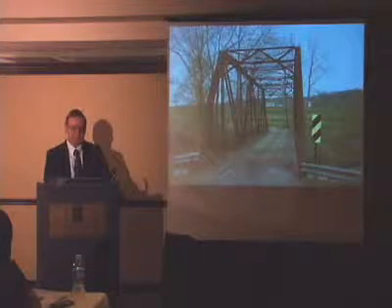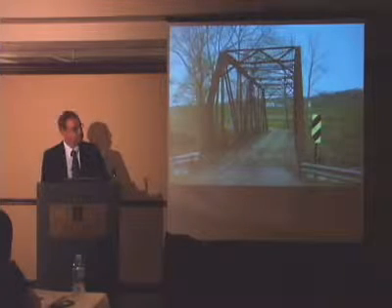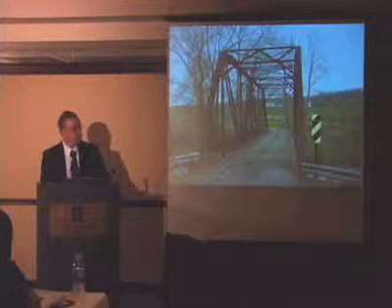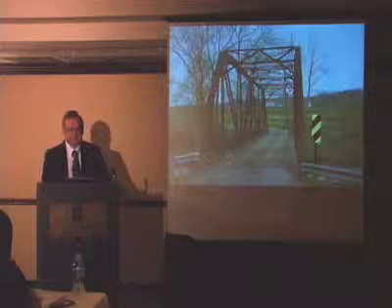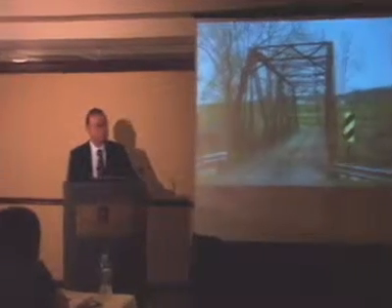So we took the bridge down, completely rehabilitated it. It was actually an old interurban train bridge. It carried interurban train cars, and so it was pretty heavy duty. So there was not a lot of work that had to be done to upgrade the bridge, other than take it apart, clean up the normal corrosion in the joints, and a couple of pieces were replaced. But everything was put back together after it was hot dip galvanized.